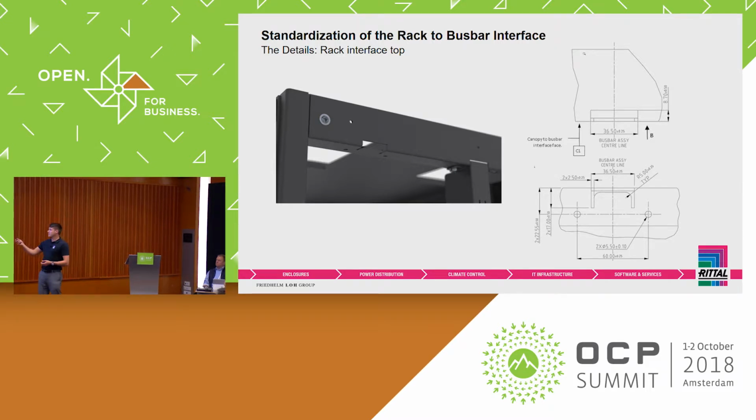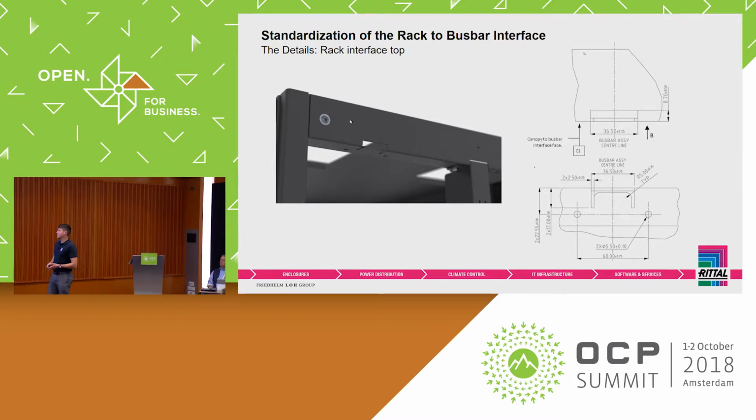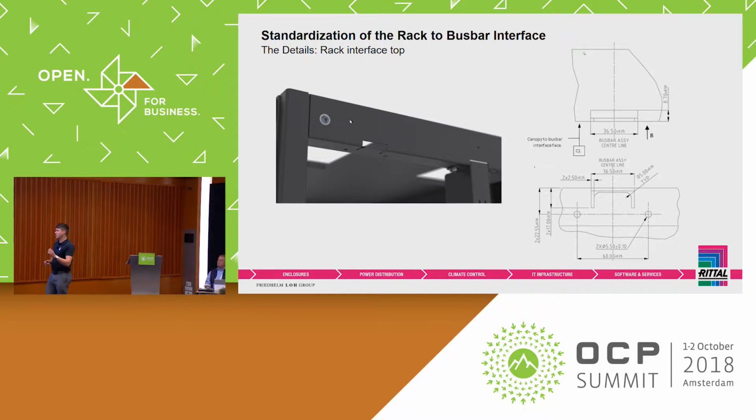At the top of the rack, as you can see here, we have an open slot with the fixing holes. So this doesn't drive the dimension of the busbar cage at all. So at this point, we want the jigs, which I showed you, that small jig in the very beginning. That's a tool that can be used for retrofitting in the field, a very simple tool. In production at our factory, we would use a bigger jig, which would sit inside the frame at the shelf level, and that would make sure that we get that correct dimension of the busbar cage for equipment engagement.